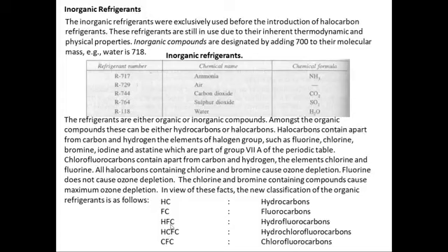So initially it was an effort to remove the chlorine from the refrigerant. This hydrofluorocarbon is one of those efforts where chlorine has been replaced. Initially it was CFC, which is chlorofluorocarbon. It has fluorine, but we wanted to remove chlorine because it was affecting the ozone layer. So we came up with the HCFC, which is lighter. It is also damaging the upper atmosphere, the ozone layer, but not as much. So further removing the chlorine, it becomes HFC.